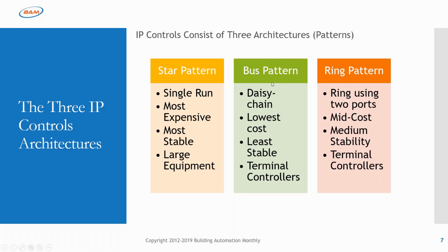The general consensus is that daisy chain can handle a lot, but ideally you want to limit it to 32 to 64 devices per segment. Now that goes against what you'll see on some manufacturer catalog sheets, but when you're thinking about troubleshooting, when you're thinking about laying out a network, typically you're thinking about laying out a single daisy chain run on a floor, typically in a vertically stacked building. And in that case, 32 to 64 devices is pretty reasonable.